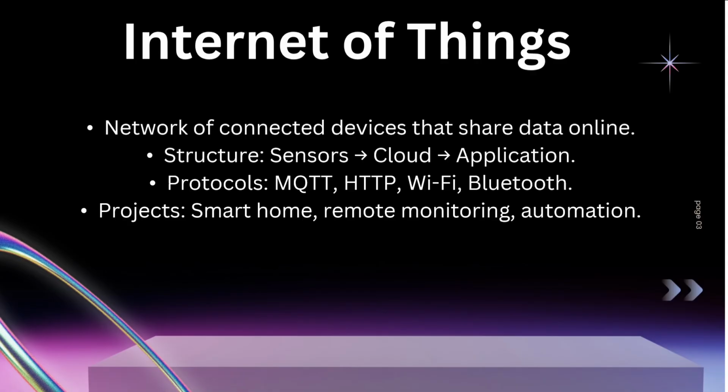So in this project, we used the Wi-Fi module ESP8266 to connect the system to the Blynk Cloud. Real-time sensor data, such as temperature and motion, is sent to the cloud. The user can control appliances like fans, LEDs, and displays directly from the Blynk mobile app.